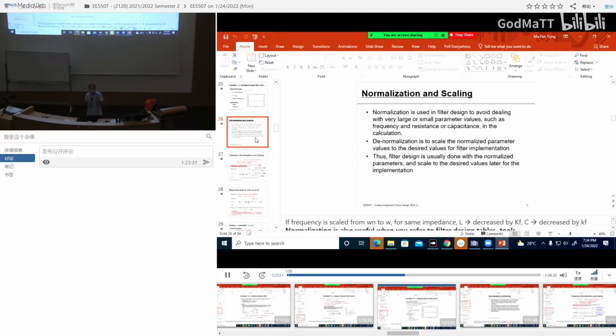If you want to know anything in between, 1 kilohertz, 5 kilohertz, you have to go from the Laplace domain to the j omega Fourier domain, and then calculate what's the magnitude and what's the phase. And then you need to know the Bode plot approximation: a straight line at the pole coming down, a straight line at the zero going up. These are all the Bode straight-line approximations.